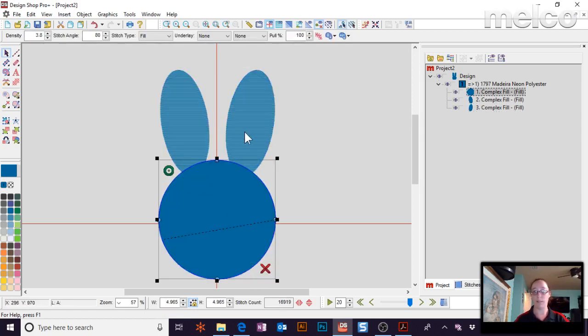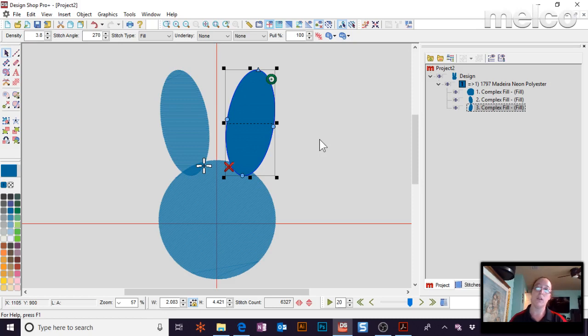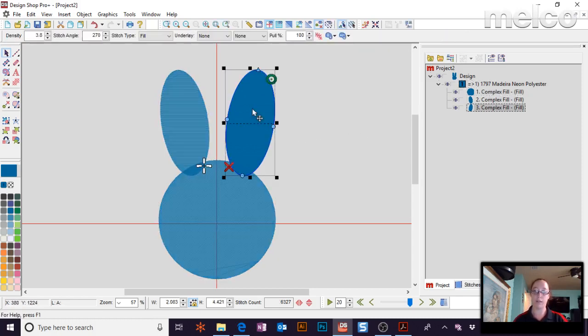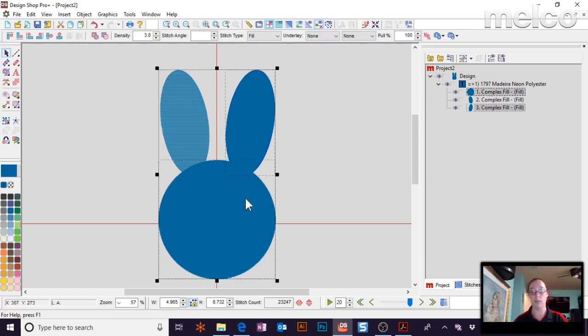We have 3 elements, so let's combine them now. When you're combining or subtracting elements, notice those two items that we had before are only visible once you select multiple things. If I choose 2 things here, my toolbar has now changed. I've got these alignment keys up here. I also have combine elements and subtract elements. So I'm going to select all of them. To do that, I clicked on one, left click, hold the Control key down, and left click on another.